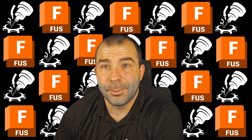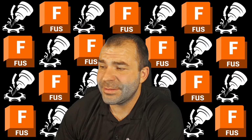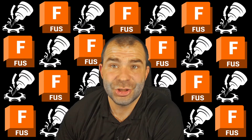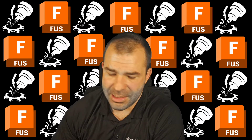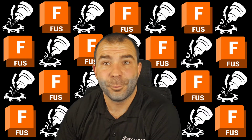Automatically based on how the post is written, and we can add this to any post, guys, you have standard versus extended. So your extended post locations, G154 P1, and if I was to change this to 15, it's automatically showing you right here that you're going to G154 P15.